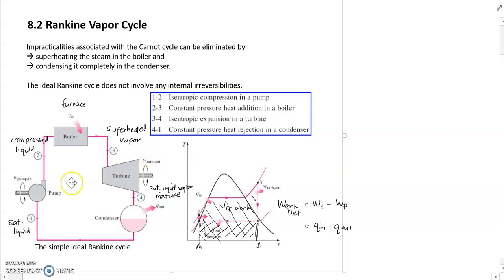So you have two pieces of equipment that involve isentropic processes. So S1 equals S2 and S3 equals S4. Your turbine will produce work by rotating the shaft connected to an electric generator. The pressure and temperature of the steam from process 3 will drop during this process to the value